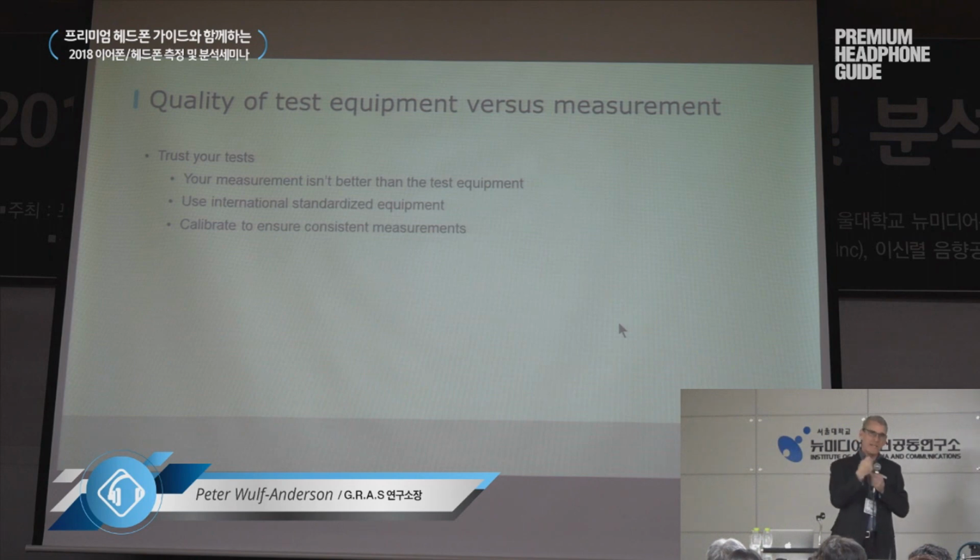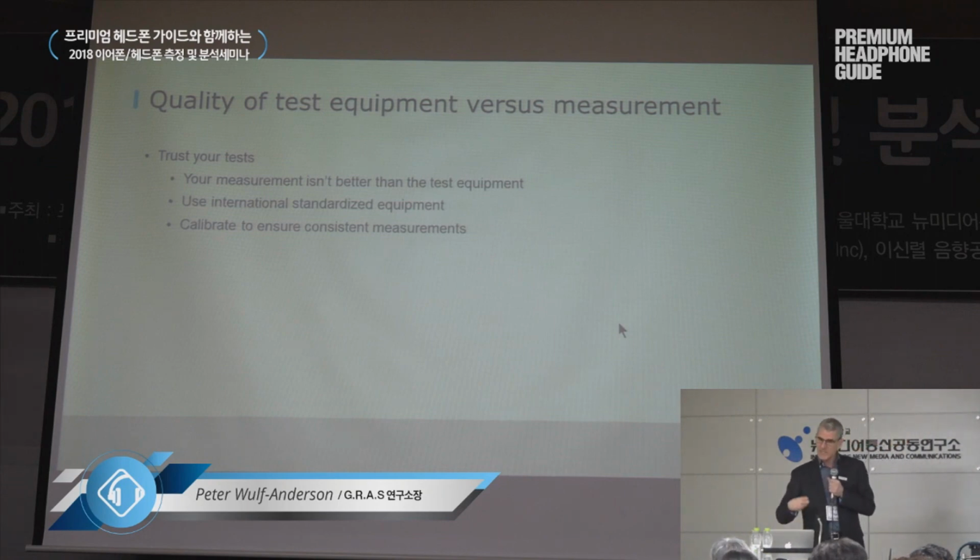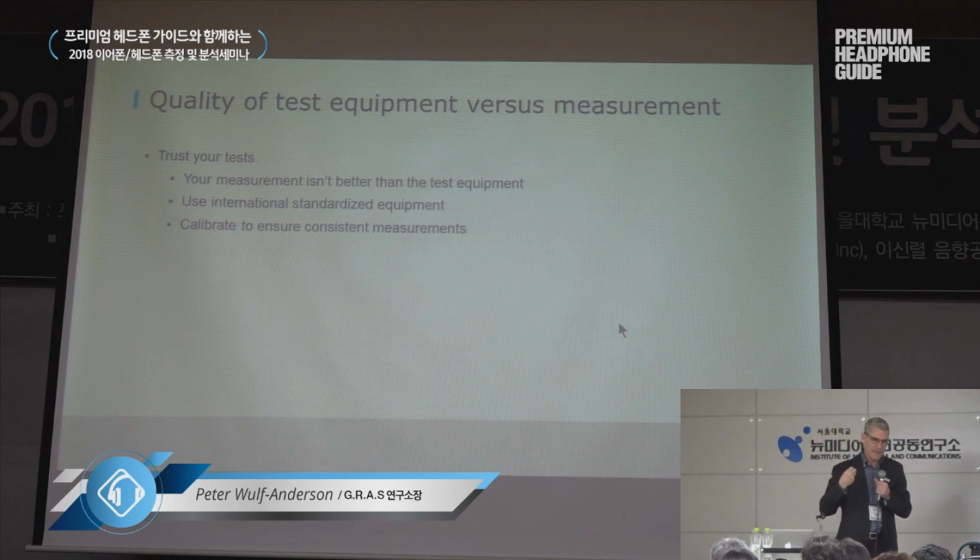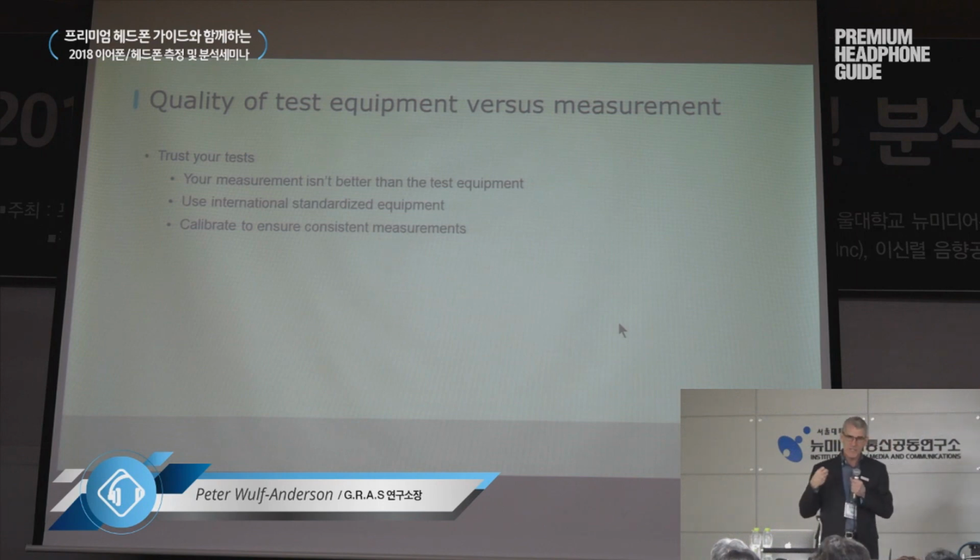So in the production line, you need to calibrate more often. Often 1, 2, 3, 4 times per day, just to make sure your setup is measuring correct, which is very important. But in the R&D lab, it might be once a week, once a month, once a day, again, depending on either your feel for it, or maybe you have some policy in the company that you have to calibrate, but it's not as often as on the production line.